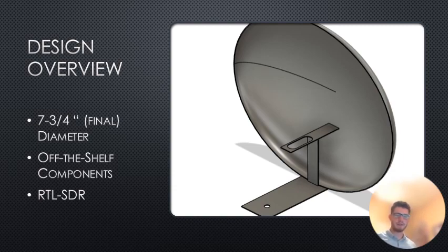Some of it is lost in the bending process in order to make it into the parabolic shape. I also designed it to be able to fit off-the-shelf components. So right here you can see this is a little channel for me to be able to fit in a receiver horn and LNB for a TV antenna, and this is based off of several experiments that I found both on YouTube and one that I found in a research paper.